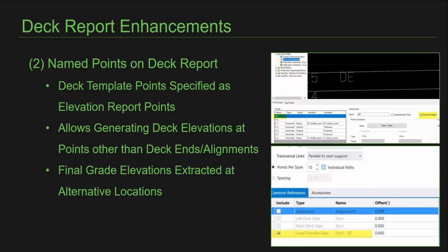The second enhancement with deck report is the option to use named points from the deck template as common references. In the deck template, there is now the option to specify a point as an elevation report point. These points will appear in the common references list of the deck elevation report dialog, and this makes it possible to read deck elevations at points other than the deck ends and alignments,